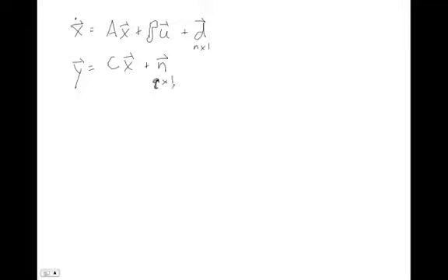So in reality, this is the system that we have. And if we make a nice control system, we'd like our system to sort of reject these things and say, on average, can I not have noise affect me super badly, and can I not have disturbance d affect me super badly? It would be unrealistic to think that they won't affect you at all, because they're there and you don't really know them very well, so it's unrealistic to think you could completely reject them. But our goal is to try and reject them as well as possible.